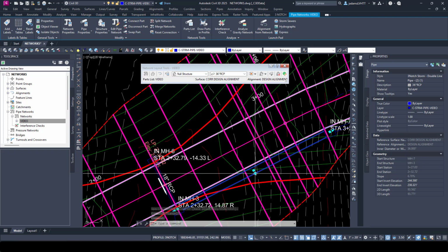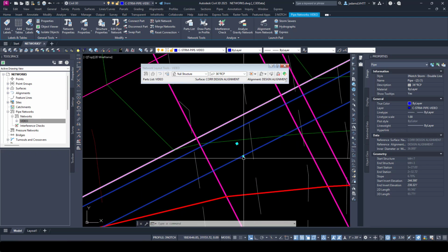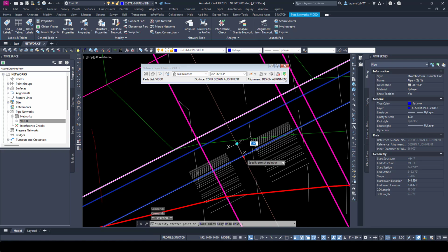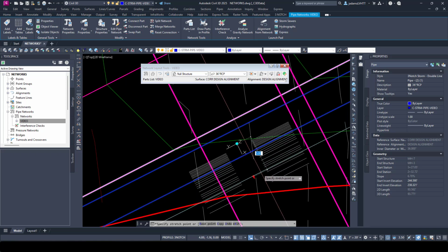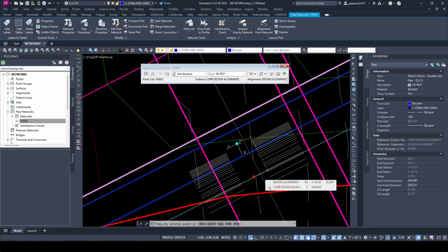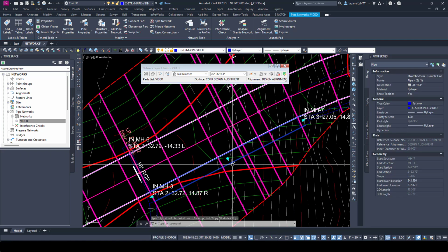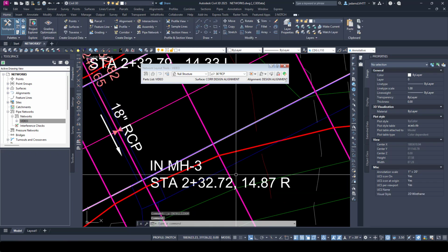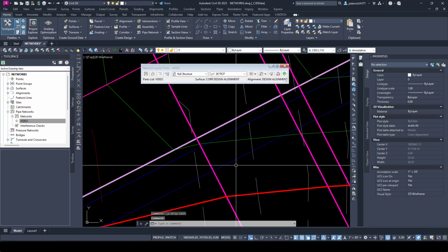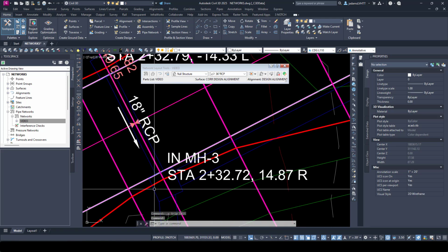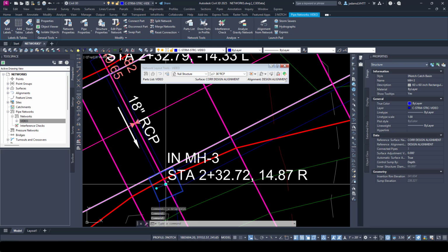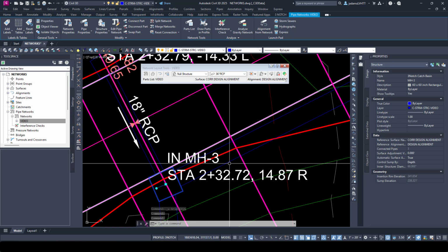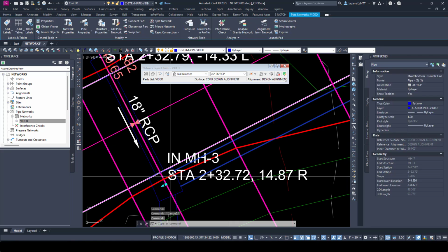I've got this grip, which is the pipe diameter grip. So I can graphically click this and you can see the marks that I'm able to pull this out and change the diameters of it if I so wish. So I could pull that all the way out to that one and have a much larger pipe, as you can see. So I'll Control Z and get out of that and get it back to where it was. So you've got those. Structures don't have quite as many grips. All they have is the move and the rotate, not quite as in depth.